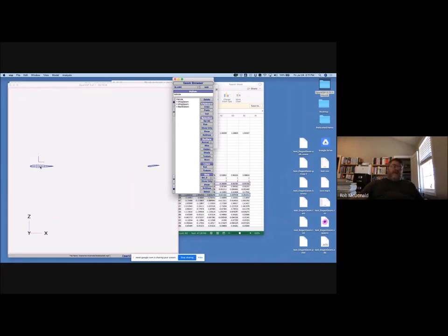a stable airplane, what you want is when you perturb it, when you bump it, or you change its angle of attack, you need to know, is that disturbance going to continue to grow, or is it going to damp back and go back to zero? And the perfect example of this is a dart, right? Have any of you played darts before? So a dart is just a really terrible airplane.